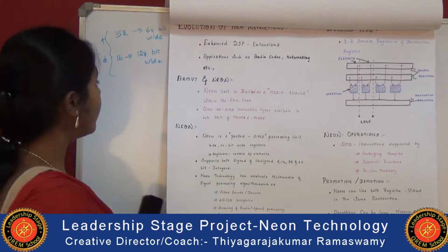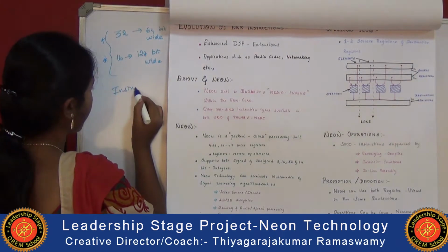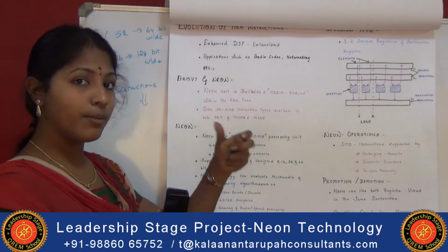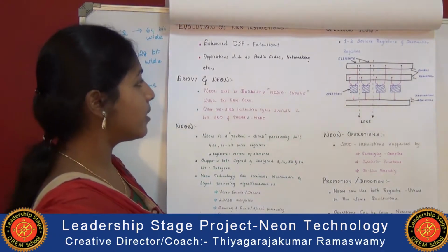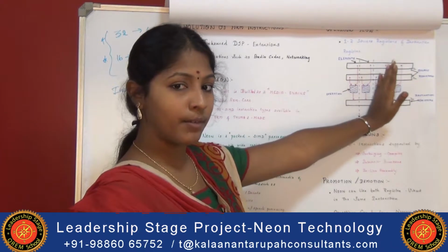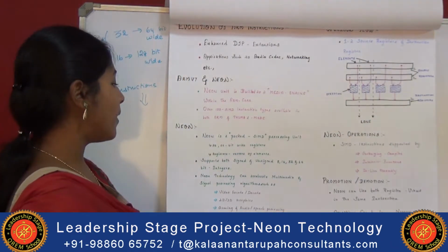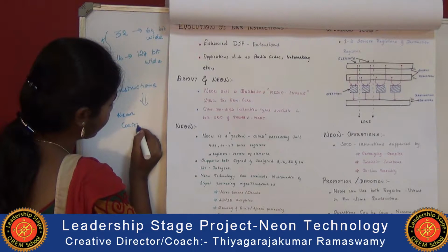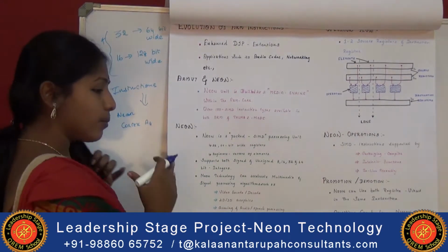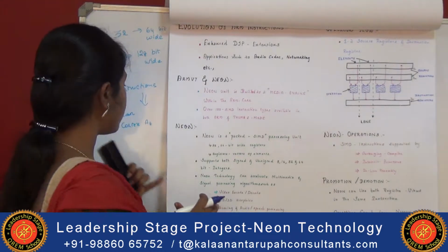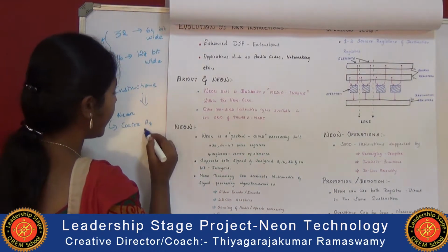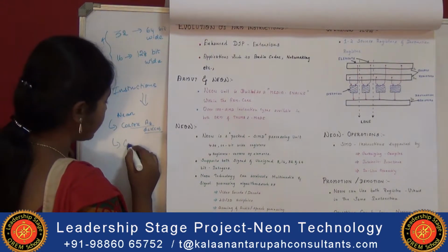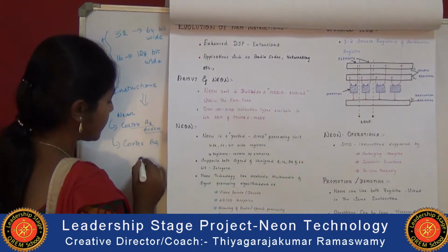Instructions perform the same operation in all the lanes. Lanes are the elements of the vector, and the instruction performs a similar operation in all of them. Neon technology is included in Cortex processors. It mainly supports the Cortex A series processors, and Neon is included in Cortex A8 devices. It has full support in Cortex A8 devices, but it is optional in Cortex A9 devices.